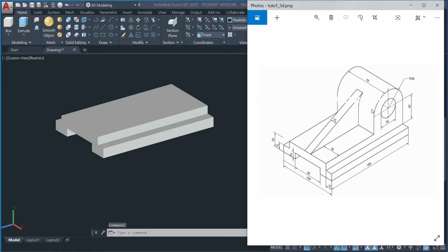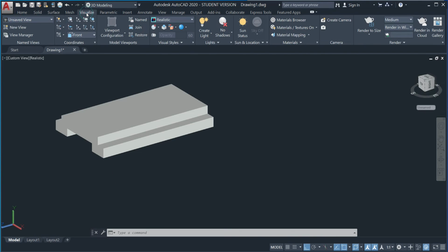So as you can see here, we were currently on this particular face, which is the front face. Now we will have to move our coordinate system to the right hand side of the object. So we will again go to the visualize tab. We will select right from here. So the X, Y and Z axes have been properly arranged.